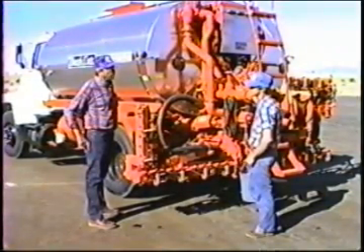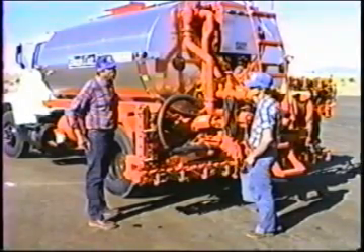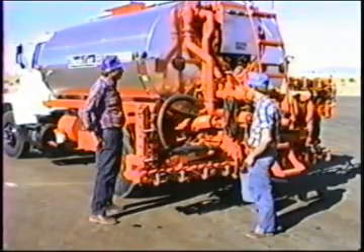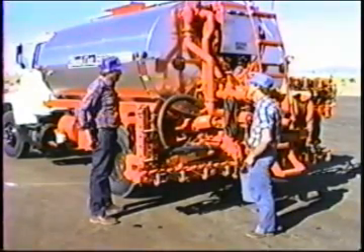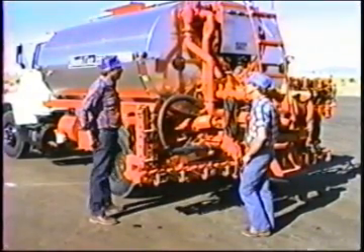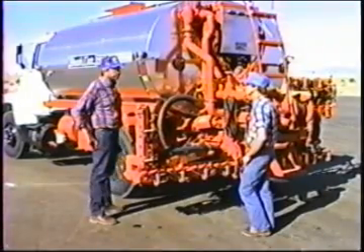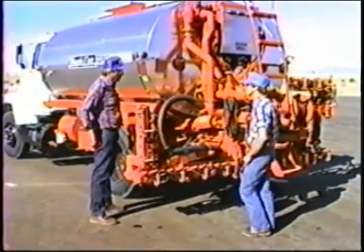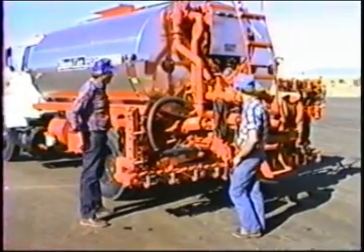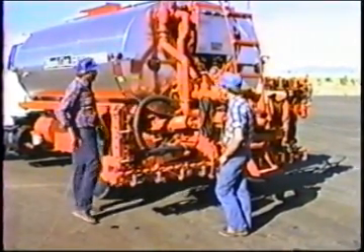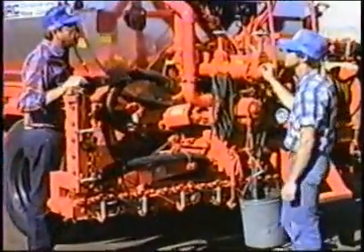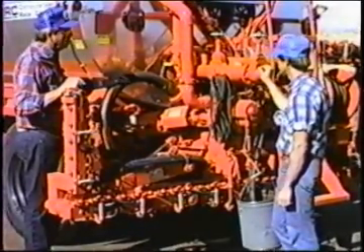And we talked before a lot about quarts and 3/10 and whatever. We've been into that just a little bit. We're going to talk about how the machine does that now. This machine uses a positive displacement method of regulating the spread rate. We are going to regulate the amount pumped by the pump by the speed of it. This is a positive displacement pump. For each revolution that we turn that pump, it's going to move a measured quantity of liquid.